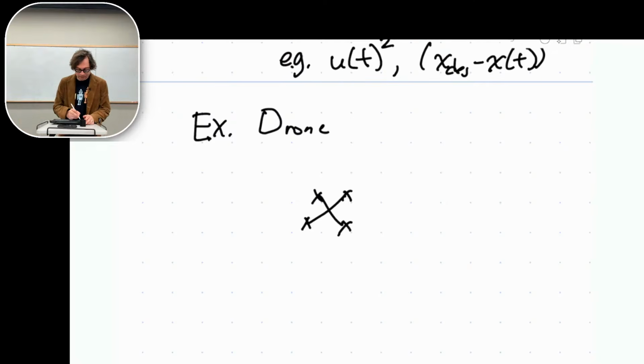All right. So we modeled this as having linear dynamics, but let's imagine that we didn't. Let's say we linearized our system. You have to linearize your system about what? An operating point. You have to choose a state and a control input you want to linearize it about, right? Let's just say we choose one. Maybe it's not very valid for very far away from the operating point. Let's say it generates a trajectory.